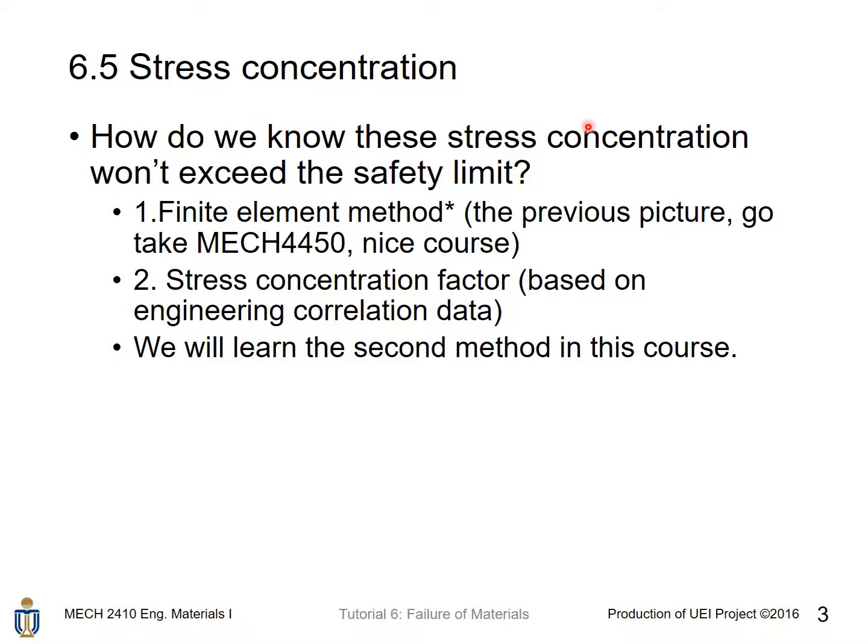So how do we make sure this stress concentration won't exceed the safety limit for that particular material? Actually, we have two methods. The first one is the finite element method, and the second one is the stress concentration factor. However, the first one will not be taught in this course.